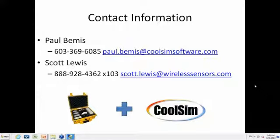And if your heat rejection system isn't operating at an efficient level, a COP of 4 or better with economizer, then you're going to be paying nearly twice for that kilowatt you're pumping into the room. So this is a very important topic, and the cost of the tools we're talking about to get a handle on this is very low compared to the energy and dollars you're going to save if you optimize.